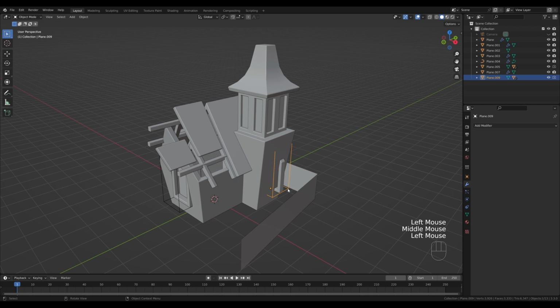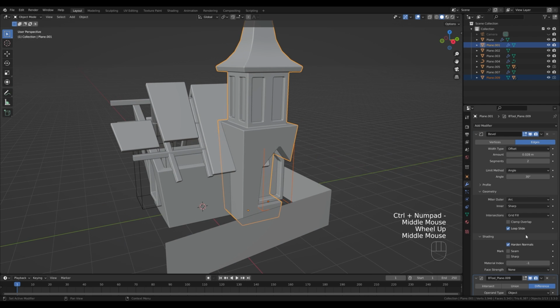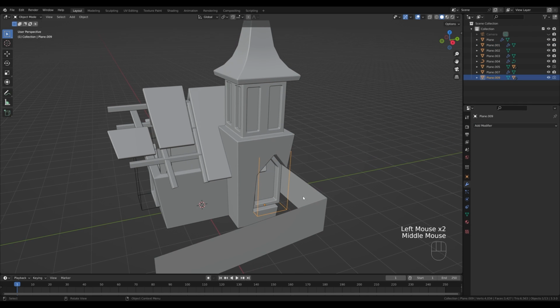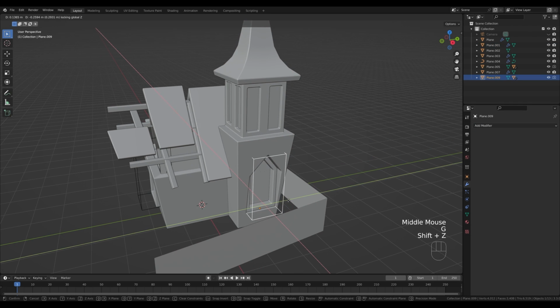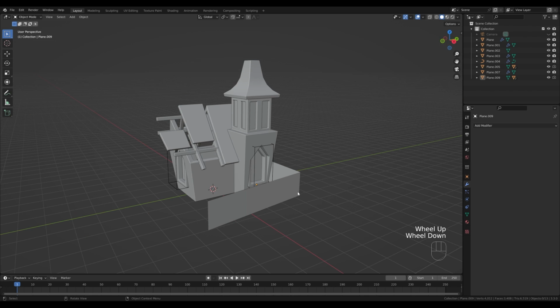And now with just the boolean cutout selected, we can press R, then Z and 90 degrees to rotate it. And shift click the tower and press Ctrl- again to create the boolean cut and move it above the bevel. And now we can just position this a little bit better, just like that, so we have a new window. And the rest is basically just about adding details. But before we do that, let's create that fence.